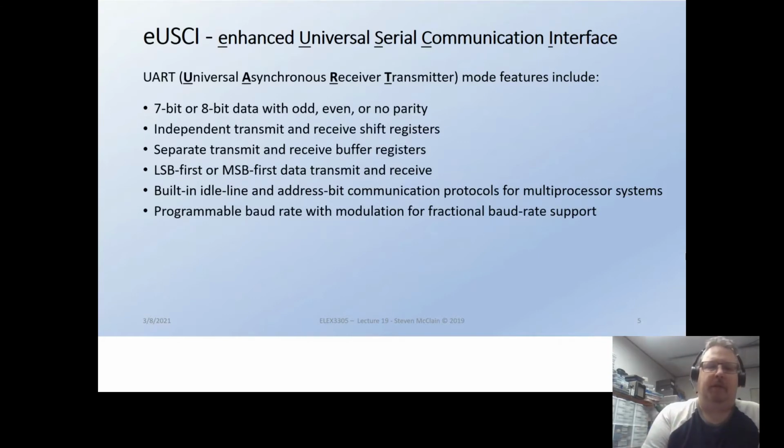Programmable baud rate, so you can basically program the baud rate to be anything. It's derived from the CPU clock, but it's just like the other ones where you can hook it up to whatever clocks. There's a bunch of different clocks, and depending on how slow the clock is, you get more and more limited in the baud rates you can choose, based on their accuracy and stuff like that. But essentially, you can think of it as being able to do almost any baud rate you want.